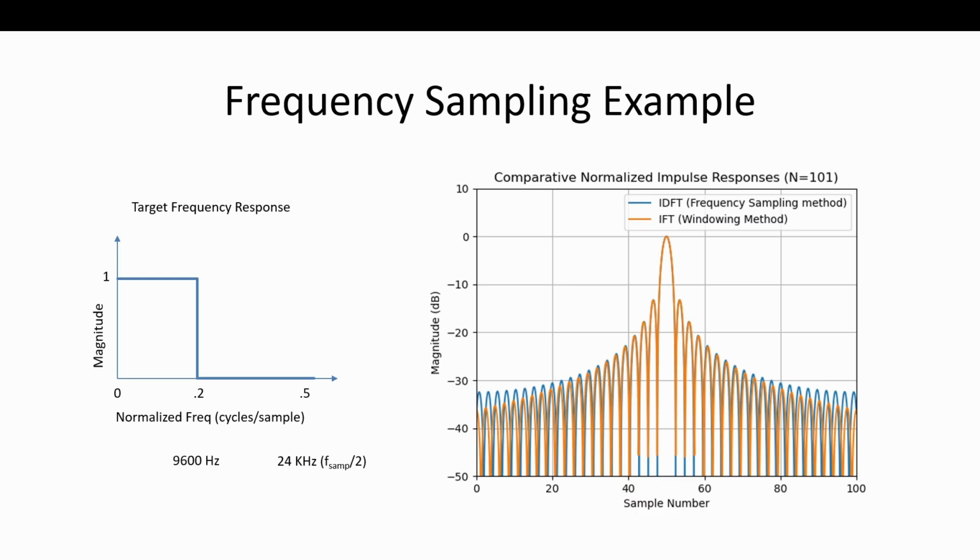It's kind of the exact same thing as if you are familiar with A/D conversions: sample it really high to minimize the aliasing from above the bandwidth, to minimize the frequency domain aliasing. It's the same thing. So you'll see that demonstrated. It's a great approach because it's quick and easy, and if you want to get frequency responses that look like the shape of butterflies, you'll be able to do that.